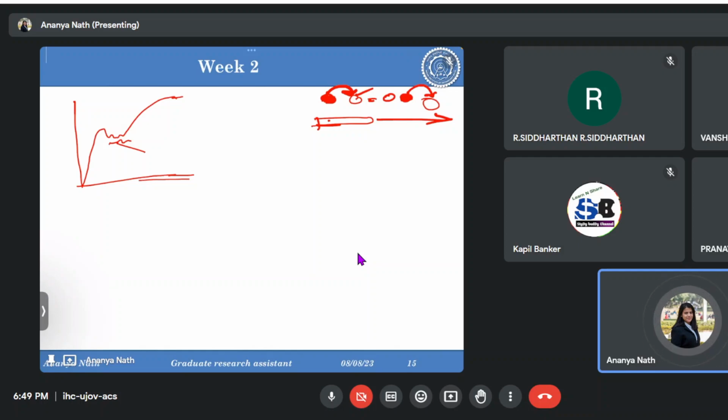What happens is, there will be an interacting or interfering stress working between this solute atom and the dislocation. So there will be an energy whenever we are adding some or raising the temperature. This temperature is a favorable condition for both of these to move faster. Whenever we raise the temperature, the dislocation will move faster, and the solute atom will also increase its speed, jumping from one position to another nearby vacant position. And what happens is a second phase precipitate forms, or the atmosphere is formed.